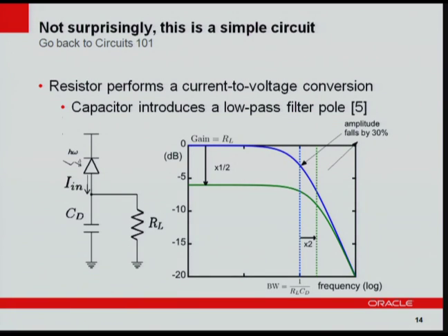This is a very simple receiver. This current gets converted to voltage as it flows through this resistor. This C_D here is an important parameter. It is the parasitic capacitance. You can think of this part as sitting in some other substrate, say silicon germanium, and here is where you want your digital signal out, sitting in CMOS.